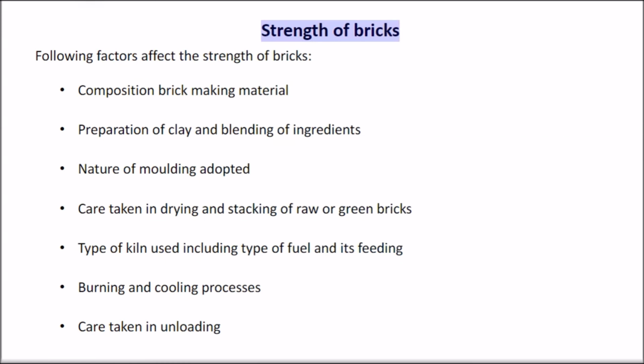Strength of bricks. Following factors affect the strength of bricks. Composition: brick making material, preparation of clay and blending of ingredients, nature of molding adopted, care taken in drying and stacking of raw or green bricks. Type of kiln used including type of fuel and its feeding. Burning and cooling processes. Care taken in unloading.